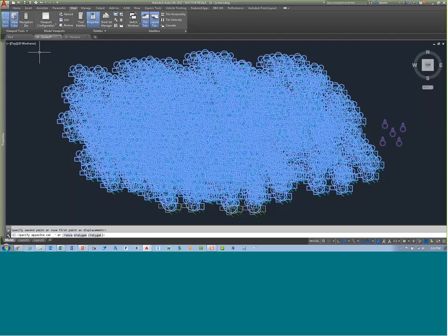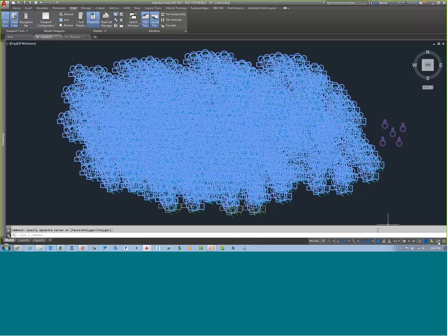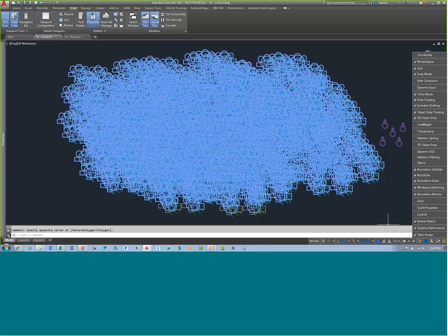You can try to do a giant window selection of all of your data, but then you sit and you wait for it to process. Then you head over to the Properties palette, and you'll see it says Varies. And if you have Quick Properties turned on, then you might be able to use the Quick Properties feature to filter.